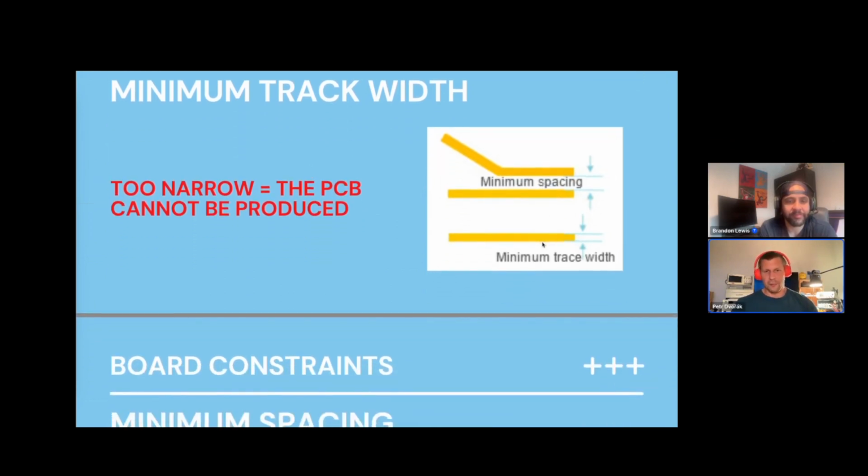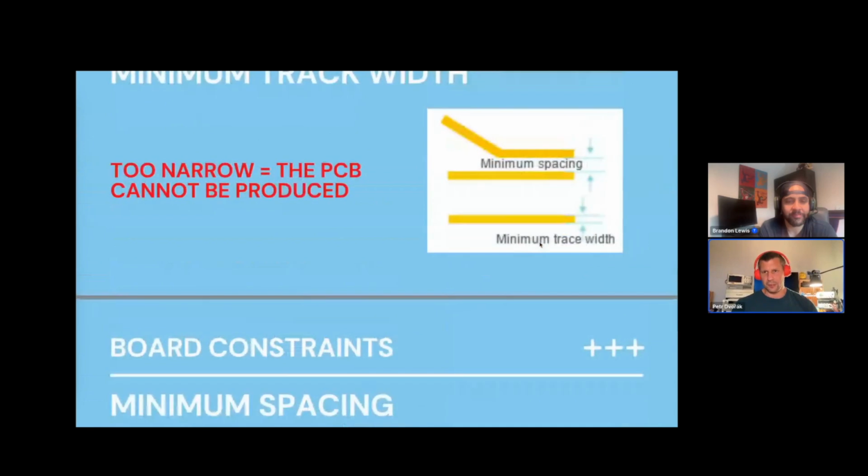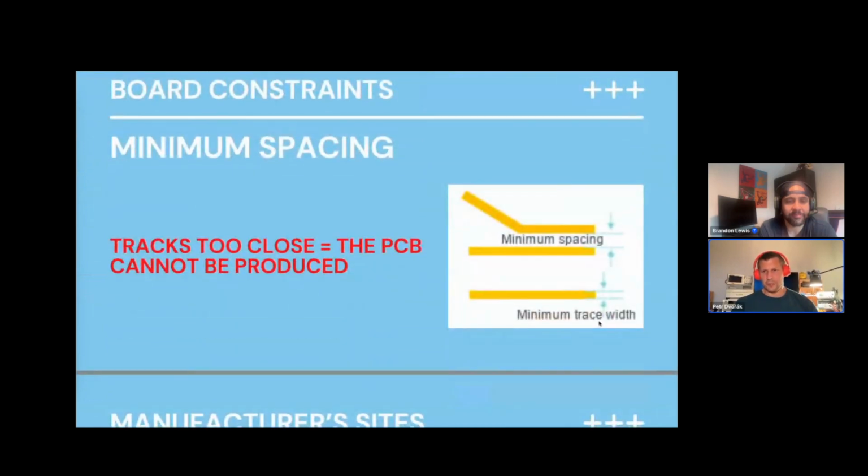The neighboring value, as you can see, the picture is the same, is the minimal spacing between tracks. PCB manufacturers show us documents or advise many numbers, but I think the most important is track-to-track clearance, because once you are aware of that minimum distance, you will be okay for the entire board, even with the distance between pads and tracks, even with the distance between THT holes and tracks and anything. The minimum clearance is everything you need.